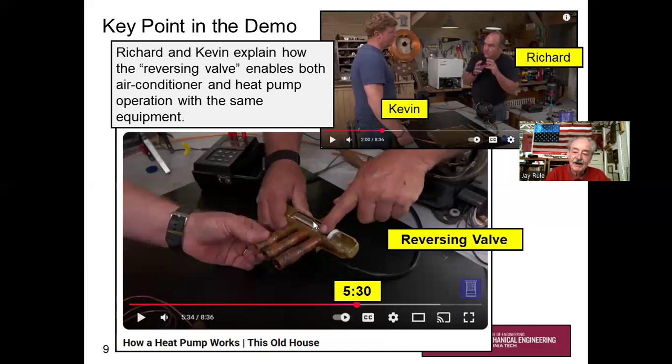And so it turns the condenser into the evaporator, and the evaporator into a condenser, depending on what season you're in. It is a reminder that you don't switch from heat to cool several times per day. You're going to select it and you need to leave it. You need to set it and forget it.